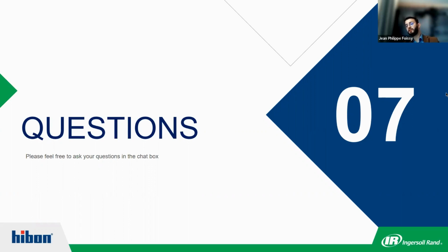What does that mean? When we install the package, we also change the flow of the water injection by monitoring the temperature at the outlet. We know that when we are above 70 degrees at the outlet, we have a risk of creating calcium inside the machine. So we will go to 50 degrees, or 40 degrees if we can achieve it. So depending on the hardness, we can also change that point.